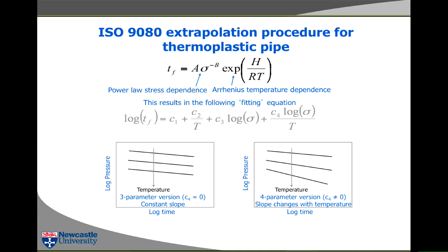So all of these curves have two terms. There's an Arrhenius term, the exp of minus H over RT or KT. Some textbooks say RT, some textbooks say KT. And then this is the creep relationship.